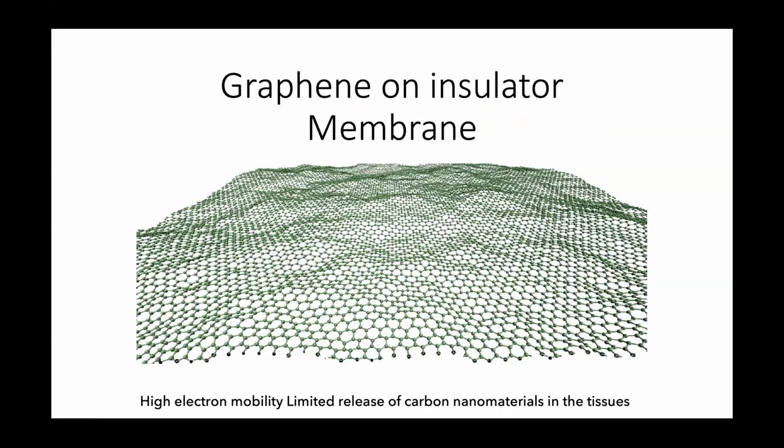We are working on a very specific material, which is a continuous monolayer of graphene, exactly 1 layer, which is macroscopic and supported on an insulating polymer membrane. It looks a bit like that. The production of this material is much more difficult compared to flakes that can be produced from graphite. It's produced by chemical vapor deposition on a catalyst, basically a copper foil, where we decompose a hydrocarbon at high temperatures, typically 1000 degrees C. Methane is used as the carbon source, which decomposes on copper.